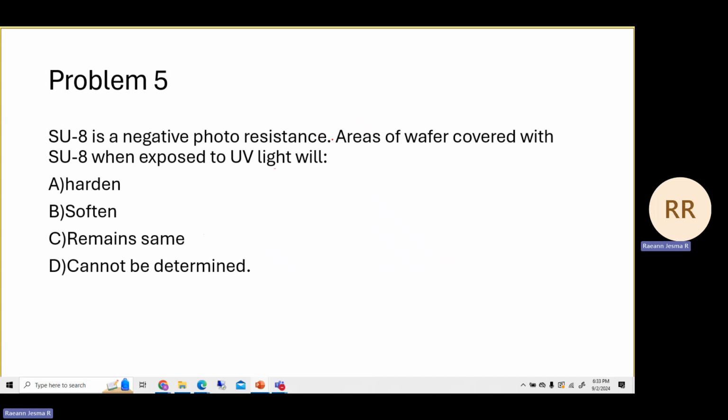So we know that photoresist has various components, and when these components are sensitive to a particular wavelength of light and are exposed to that wavelength, the properties will change. So in this case, what changes is their solubility to the developer, depending on the intensity of light as well as the regions which are exposed or not exposed.